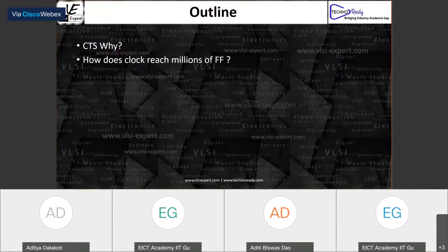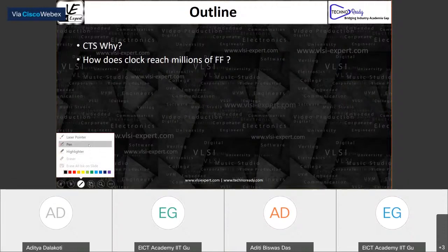So that's why design of a clock tree is always a trade-off between how much power you want to spend on the buffers. If you put more buffers, you are putting in more power, and ideally you would like to reduce that, right? But you still want to maintain enough slew rate that you do not add noise. Now, if the second point I made was the only point of concern, right?